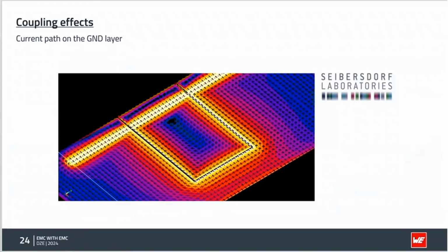What happened? Well, at first we thought, yeah, easy explanation, capacitive coupling. And then we realized, well, the signal is a 1 megahertz square wave, and at that frequency range, you would need a massive capacitance to have capacitive coupling. So what happens is you have eddy current, eddy current inducing a flow in the other direction.